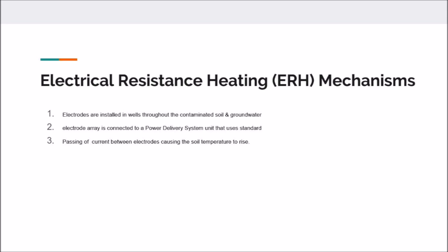This increased temperature results in the volatilization of contaminated compounds into the vapor phase, so they can be removed through vapor extraction techniques. This heats the subsurface to temperatures that promote evaporation, increasing the subsurface temperatures beyond the point that most VOCs and NAPLs are used to. Yet they are applied at low and moderate temperatures. This is a helpful procedure because it can boil water in all soil types. From the heating, that can increase the biological degradation and the chemical reactions.